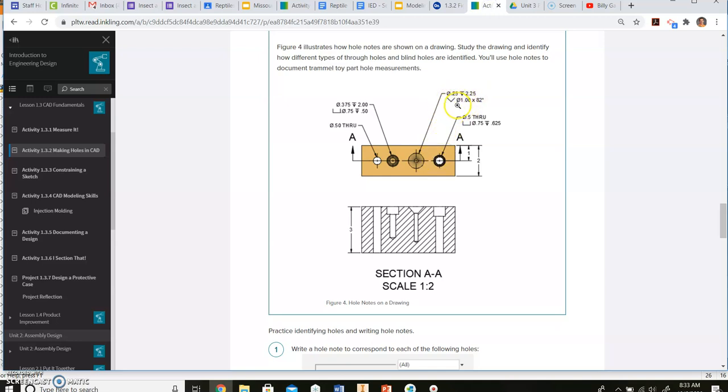That's what this kind of upside down portion of a triangle, a greater than sign, looks like. It tells us the diameter of the hole itself is 0.25 and it goes 2.25 inches. So again, it's a blind hole, and it's got an 82-degree slope on it as it goes down, starting at 1 inch diameter. So we'll go back.